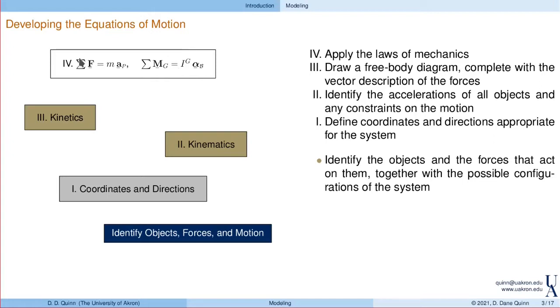But again, the last thing I'm going to do is apply the laws of mechanics, right? Because that's where I get the equations of motion from. When I talk about problem-solving procedures, I need to get myself to the point that I can do this. What's involved in that? The thing that I'm going to do right before is describe the forces. So I'm going to draw a free body diagram, and I'm going to properly label all the forces. And that's going to go right here in the right-hand side of each of these equations.